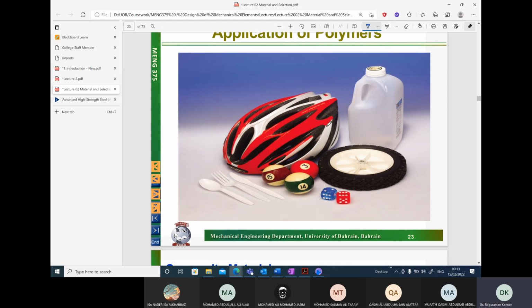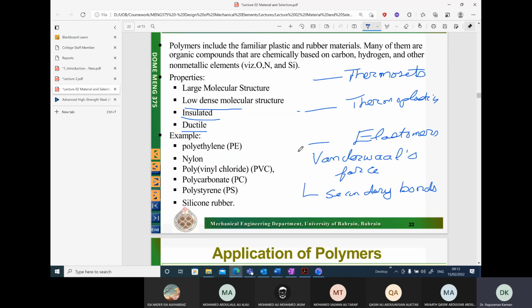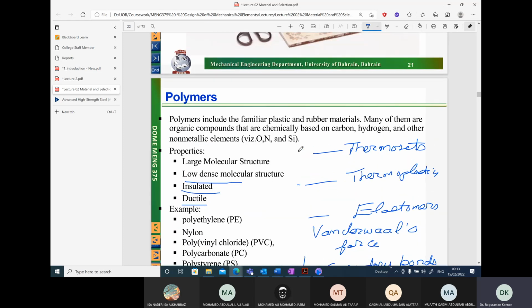Even if you go to a temperature of 70 degrees centigrade, these materials undergo probably chemical changes and it will get burnt, and it will lead to very less strength at these lower temperatures as well. So in case of polymers, often they use creep strength of the material. Okay, creep strength of the material at high temperatures.